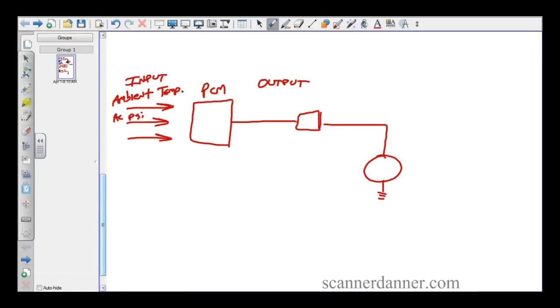What else? You've got to press something. That is an input. Very good. So we have what we would call an AC request in some way, shape, or form, whether that's the defrost button that automatically turns it on, or if it's a separate AC button on the dash. We'll throw two more in there. Two more that I'm thinking of that would be involved with the engine computer system, not necessarily turning the clutch on, but when would we want to turn it off?